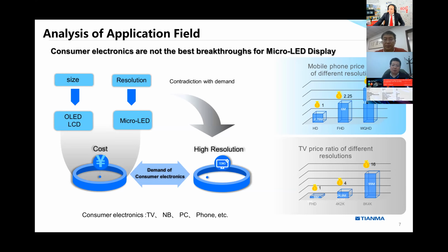And while at the same time, with improving resolution, yield is not going to be compromised for LCD and OLED. But for Micro LED, the yield will be impacted as resolution is improved. Now, talking about TV from 2K, 4K to 8K, we're going to have at least 100 million Micro LEDs needed for the large size panel and display. So I think that technology-wise and application-wise, Micro LED is a very difficult technology.